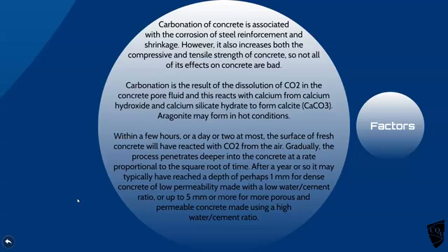It can be quicker on poor concrete or porous concrete, but eventually it will get all the way through the concrete. When it gets to the depth of the reinforcing rods, they're exposed to corrosion, they will expand and they will crack, and you'll get concrete failure.